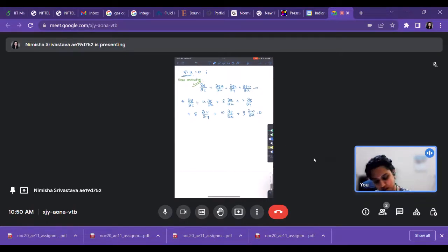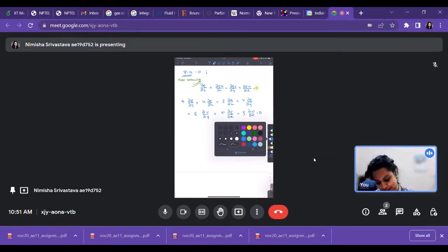Unless, and over here we have a 0 in this case, because fluid cannot be spontaneously generated unless we have a source of some kind. But for any flow going through a pipe or any place actually, the source term should be equal to 0 unless there are some generation terms, but we'll not talk about that much. So this is the whole expansion of all of the terms that I have in my mass continuity equation.